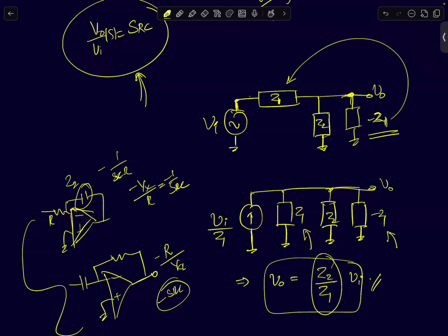There are some specific devices which tend to have negative resistance properties. But for a monolithic solution, such devices may not be feasible. Monolithic meaning we want everything to be a circuit level solution, which includes MOS transistors. I want it to be a MOS transistor based circuit. Then I can't use some specialized devices like, as you guys said, silicon controlled rectifiers or Gunn diodes. I'll not be able to use that.